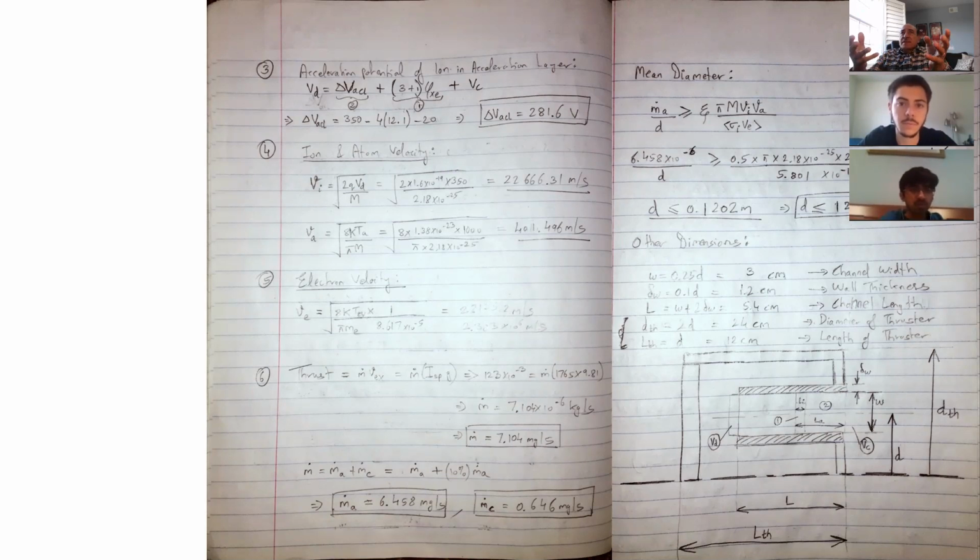From the ion velocity, you match it with the specific impulse, then you get the mass flow rate. You have to have a certain mass flow rate, like 7 milligram per second. And from that, what I don't understand is this formula. In the mass flow rate, you have to have some reactions inside the chamber, apparently, to maybe ionize most of that mass.